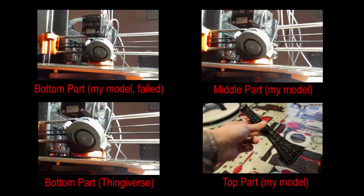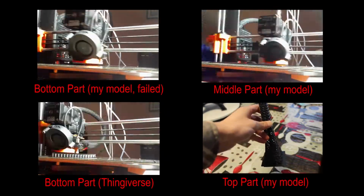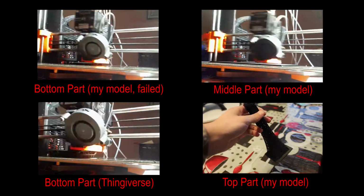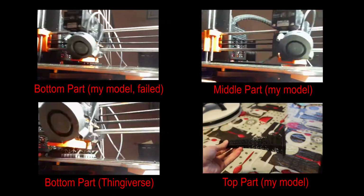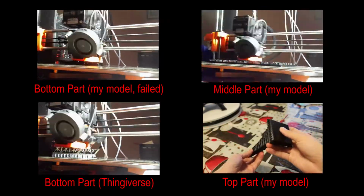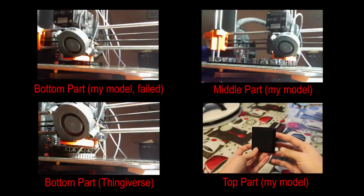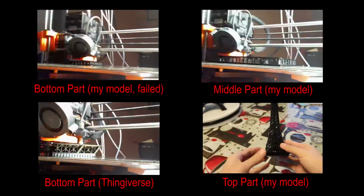As you can see from the results of the prints here, the top two sections of the tower came out relatively okay. They're not perfect, but at least the girders are intact and decently printed. If you look at this bottom part though, it is just bad. The girders are too thin as supports as the print gets built up. Also, the slant is not helping.